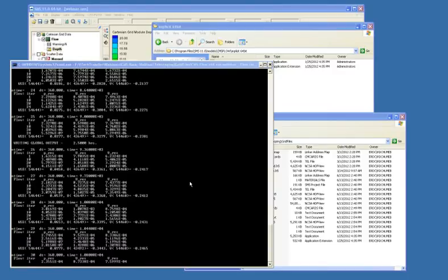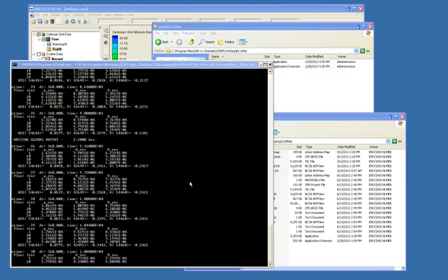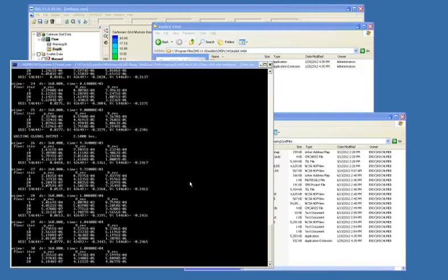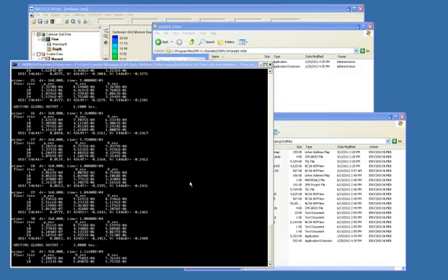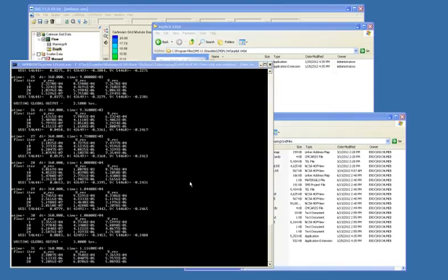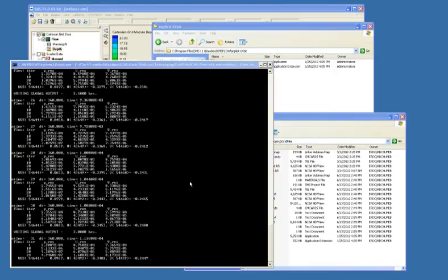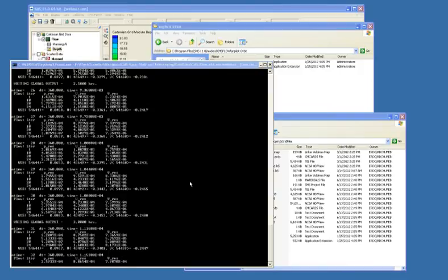Another question is, can you define cell strings in the middle of ocean cells and define flow and salinity boundary conditions to these cell strings to simulate a marine outfall? Right now, in SMS 11.0, you cannot. The only way to put cell strings is along external boundaries and at locations where there is a land and water interface.